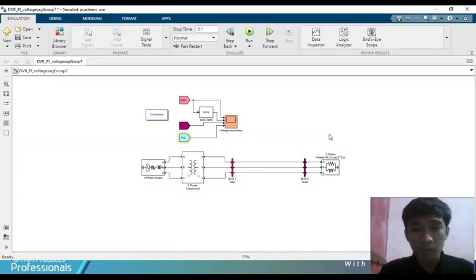Okay, this is the grid that we designed with the load side before the voltage is applied to the solar PV system. The script is designed for a normal condition where no fault or error occurs. So this is the three-phase supply in the transmission with the voltage supply of 11 kilovolt at 50 hertz connected to the three-phase transformer, 1 megawatt and 50 hertz. This impedance of resistor and inductor transmits to the load.